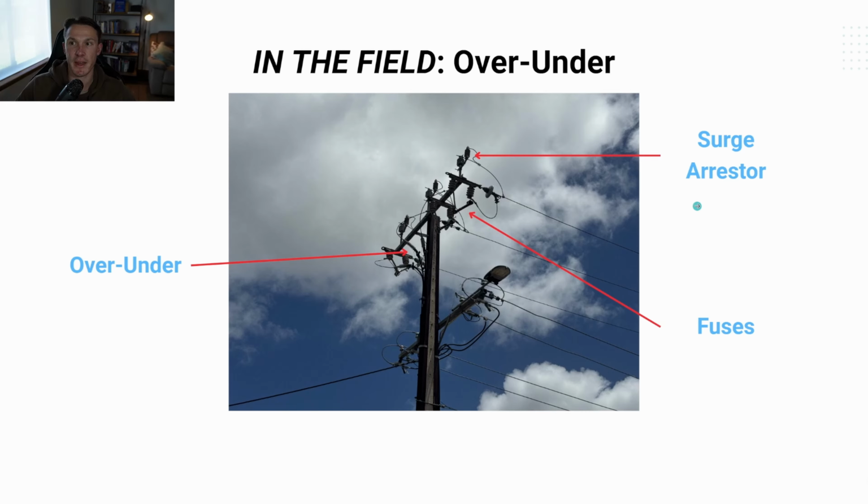Another thing I'd like to point out on this configuration is what they call surge arresters. Effectively, if a bit of, let's say, lightning struck this line, these surges are designed to absorb that, effectively providing less resistance than the insulator and the line. So rather than blowing the insulator, you blow these surge arresters rather than getting further down.